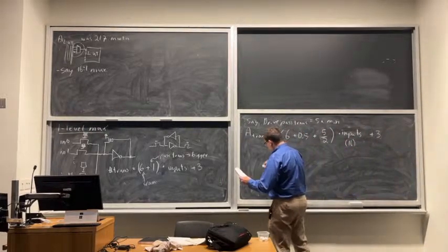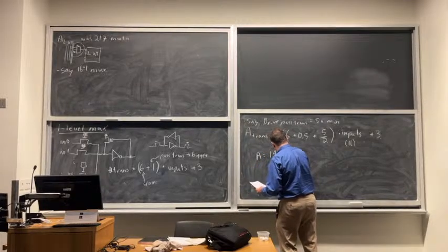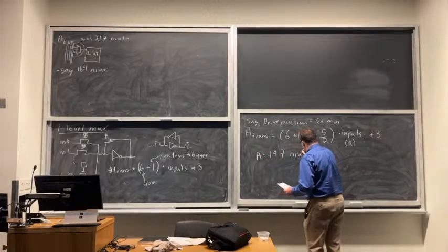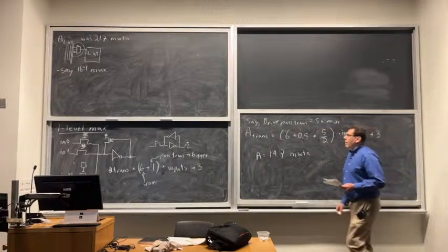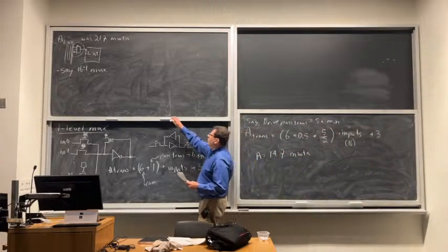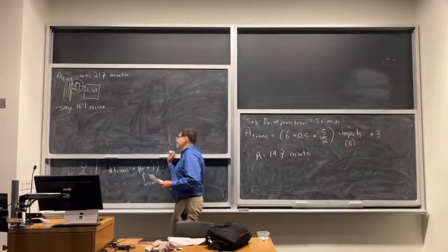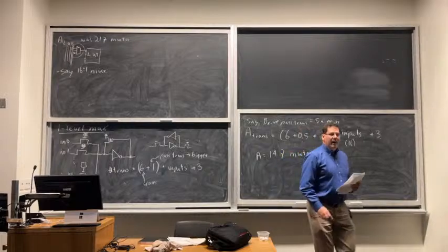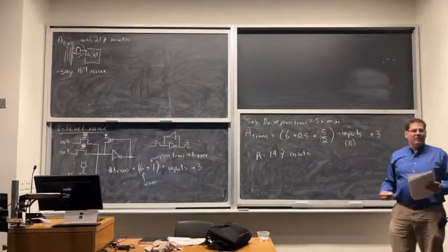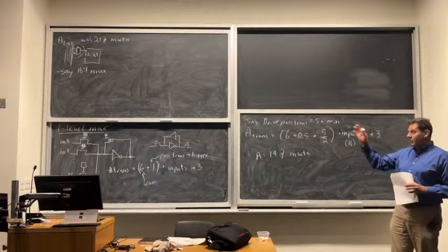And if I plug in those numbers, I get an area of 147 of these minimum width transistor areas. Okay, so if I compare that back to my lookup table size, it's not as big as my lookup table, but it's about 60% of the size of my lookup table. And I'm going to need 4 of those muxes. So it's showing that my programmable routing is pretty expensive, because this is only part of my programmable routing.